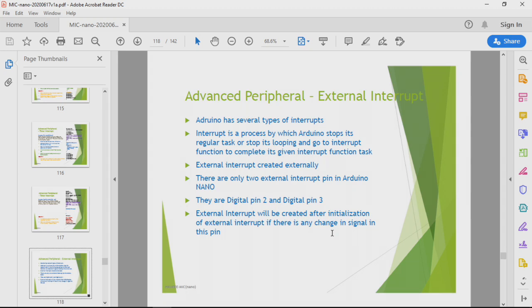Okay, external interrupt is also useful and popular in MCU projects. Why? Because most of the time the external device, maybe a temperature sensor, once the sensor reaches some figure, will make an interrupt request to the MCU to alert it to get further processing. So what is an external signal?